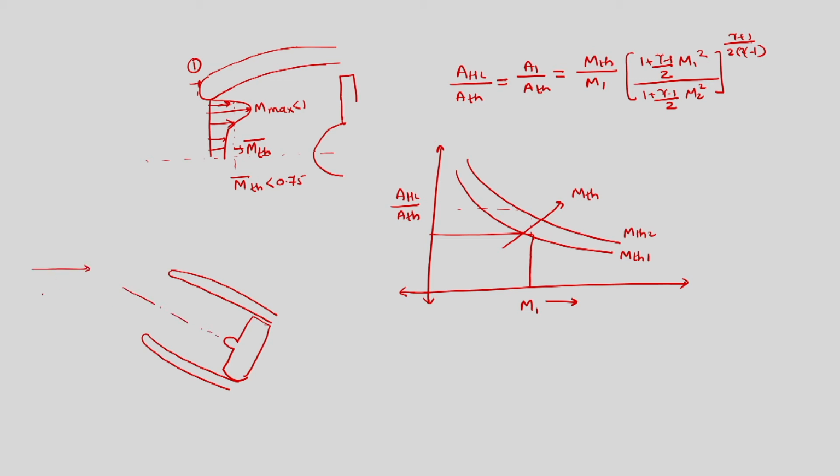And flow is coming like this, due to which we have a big separation here in this region, which would lead to lower mass flow rate. So, intake should be properly designed to cater to a range of angles of attack. Having said this, we will move towards the supersonic intakes.